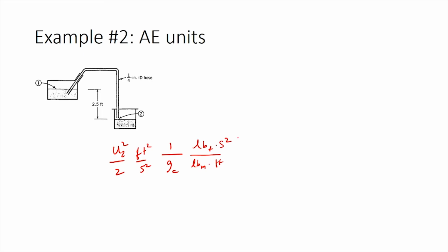So, this would be the units for Gc. Here you would have the second squared cancelled, feet cancelled, and you would be having the final units as feet times pound force divided by pound mass, which is the same units as the friction factor which has been given, plus you have 32.174 which is the g value in the g delta z.